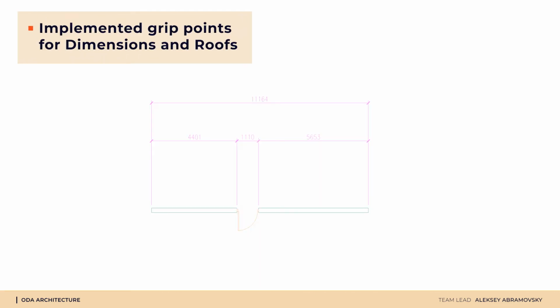Grip points are a UI feature which allows you to modify an object simply by dragging them. Nearly every object in a drawing includes basic grips, which are displayed at key points when the object is selected. Using basic grips, you can quickly modify the size, shape, or location of the selected object. In addition to having basic grips, many objects have grips that are relatively unique to the type of object. These grips provide access to additional options.